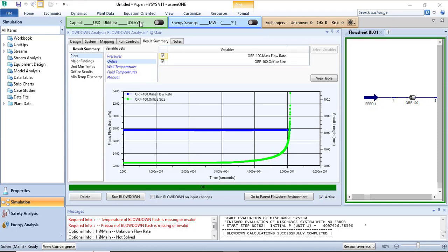Hi guys, let's look into the results. For the oil phase, you can see that after some time, when the pressure drop is minimum, the CV becomes the maximum. The same thing happened here. When you approach very near to that 90 bar G, the maximum size that we require is around 100 something mm. So 100 mm corresponds to around 4 inch, 4 inch something.